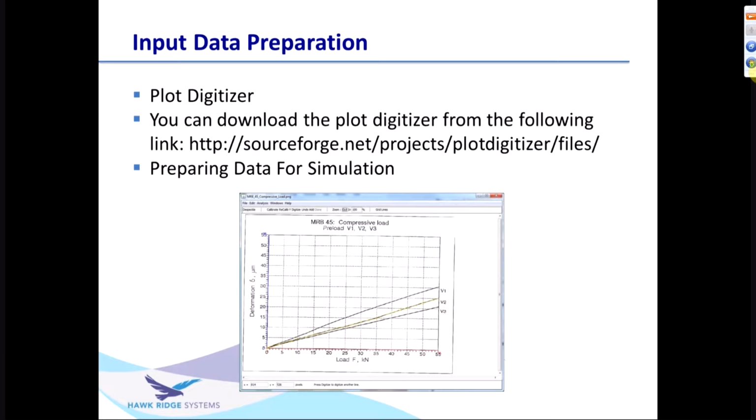And as I'll show you in the setup of the analysis, what I'll mention just for now is that when defining spring connectors in SOLIDWORKS Simulation, you define the stiffness in a normal direction and a tangential direction as either a distributed stiffness across an area or a total stiffness. And the linear rail data that we obtained needed to be converted to values that we can use as inputs for the spring connectors.